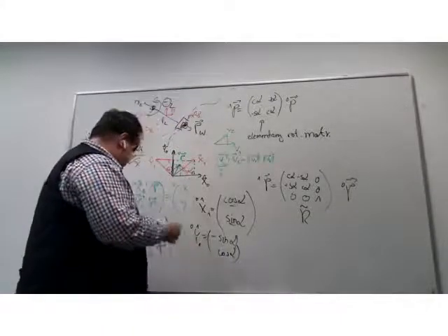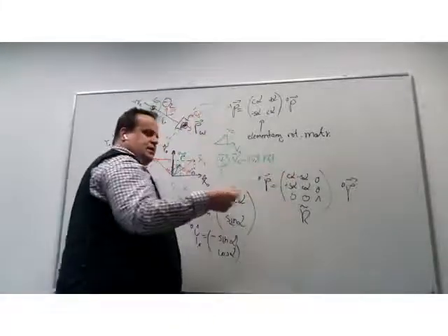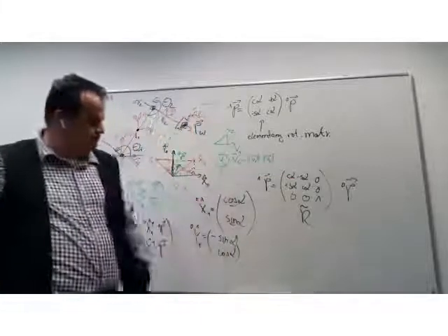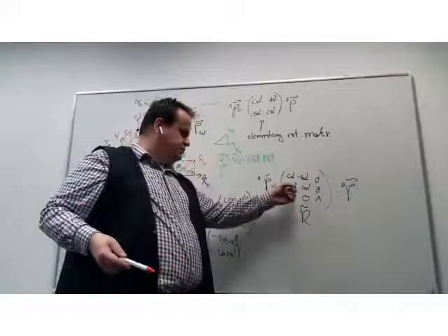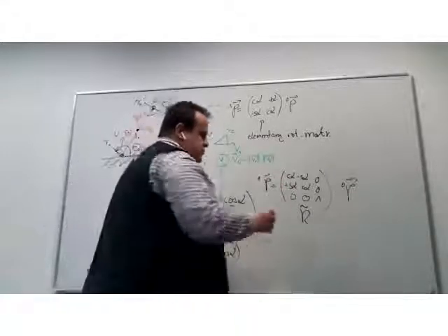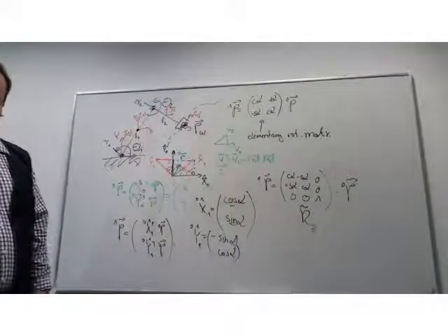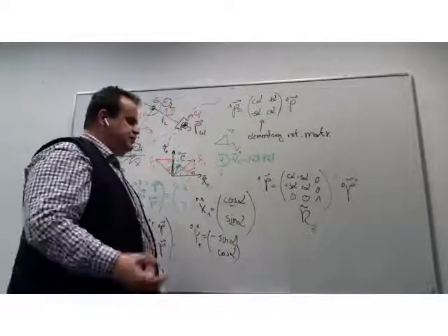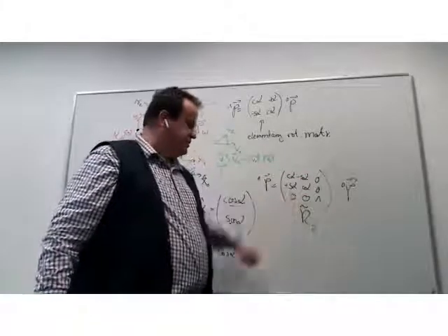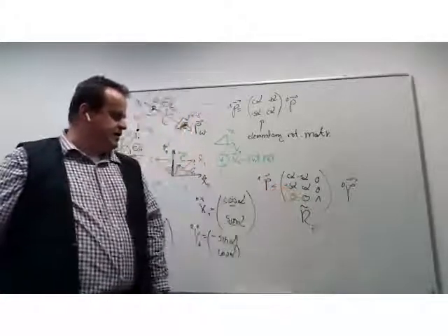If I plug in minus in the black one, cosine plus or minus is the same, so that's why it says cosine. Sine of a negative value is minus sine. Same is here, so the two minuses give the plus. So that's why the elementary rotation around Z is basically something which does not change the Z coordinate, and it has the cosine and sine expression like this.